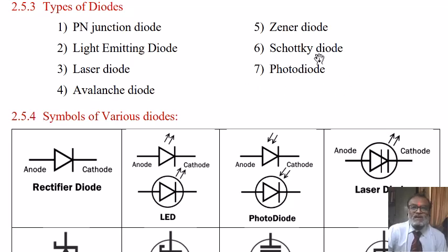Photodiode is a diode in which when the light falls on this PN junction, it generates the carrier. So light photons generate the minority carrier around the PN junction. Photodiodes are normally operated in reverse bias. In forward bias case, they are similar to an ordinary PN junction. Photodiode utilizes the special photosensitive material which can convert the light photons to minority charge carriers.